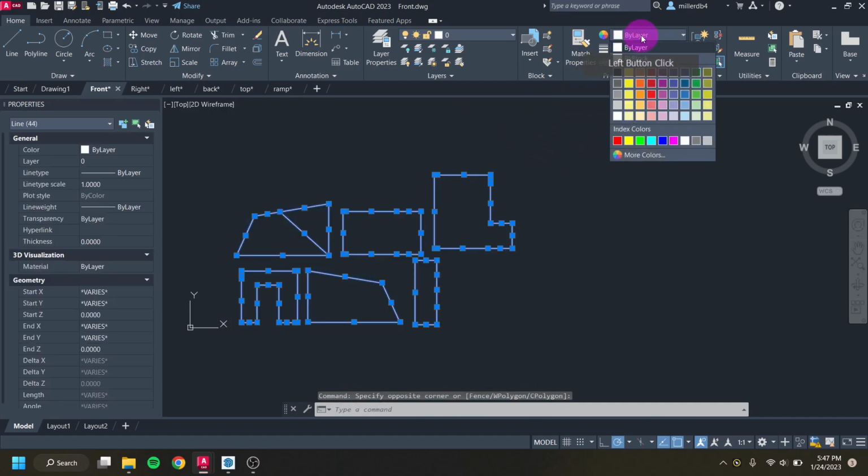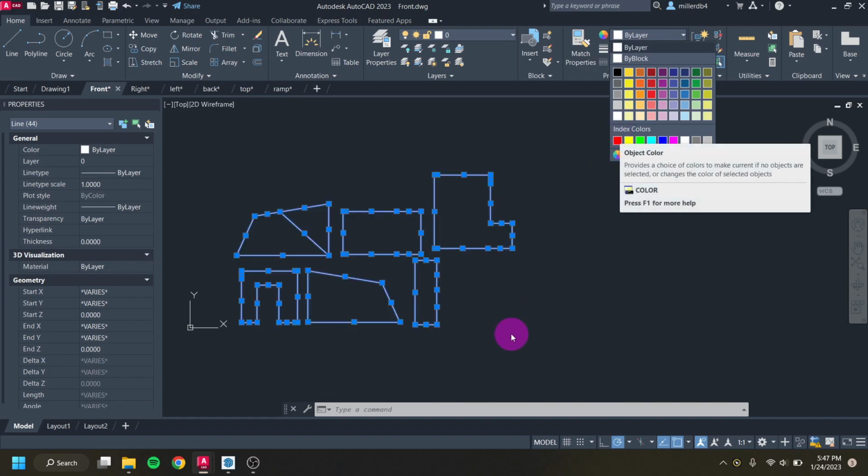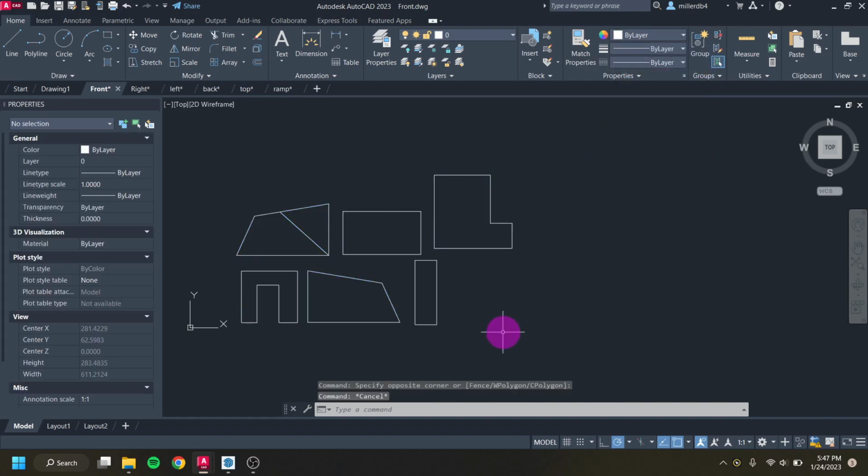And then highlight everything, and I can either do just a property override here to change its color, or I can create different layers in order to do it. So that's how I can export it from SketchUp as just the faces for my model to laser cut.